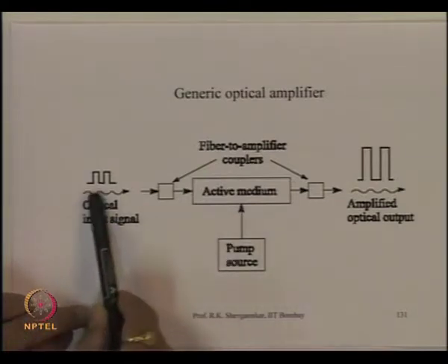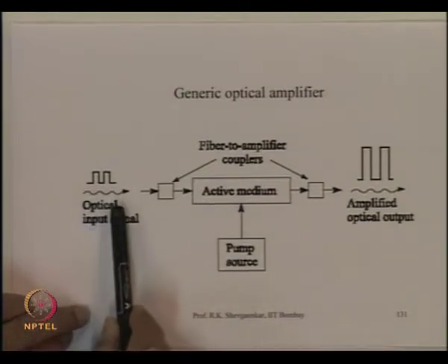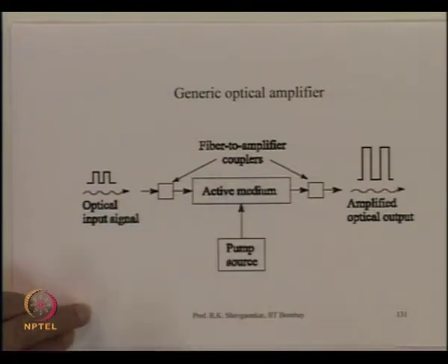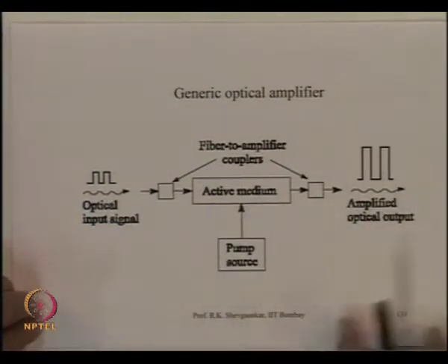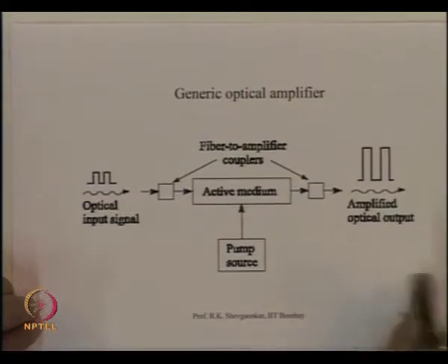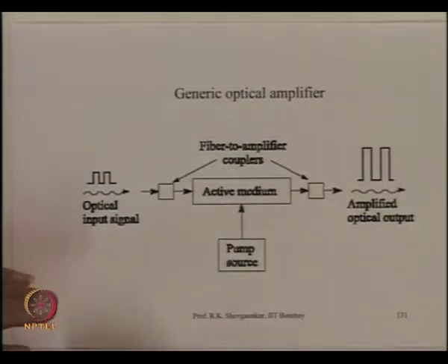And then if you put an optical signal which has a frequency equal to the energy difference of the two energy bands of the medium, then the signal gets amplified because of the stimulated process. So, even this system is the same as a laser system, only now the medium is the optical fiber.